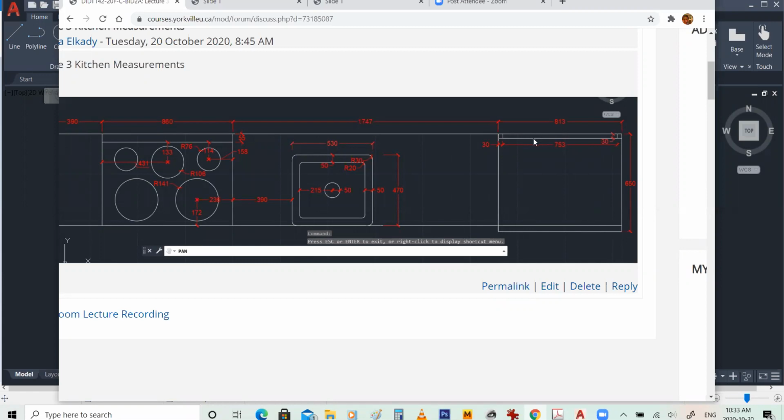Okay, and we also need to account for creating an inside part for the fridge back that is offsetted. We're going to offset the segment to the inside 30 millimeters as well, and then we're going to add those small indentations here, offsetting those small segments to the inside 30 millimeters as well.